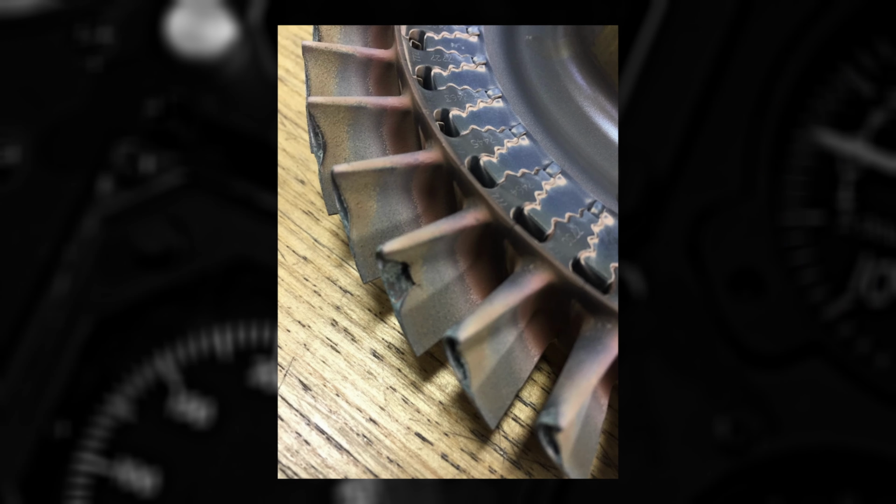Damage to the airfoil of the HP turbine stages from erosion, corrosion, burns, salt, or laterite deposits, cracks or loss of material on diffusers and stators, and rubbing. The damage to these critical parts results in a decrease of turbine efficiency and reduced engine performance. These borescope images were sent by customers requesting assistance with determining the type of damage in their engines. We receive these types of pictures and questions often.